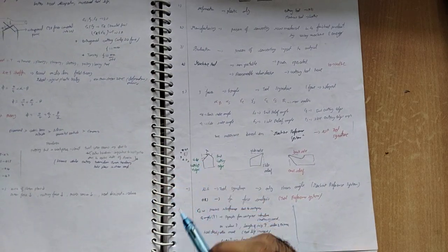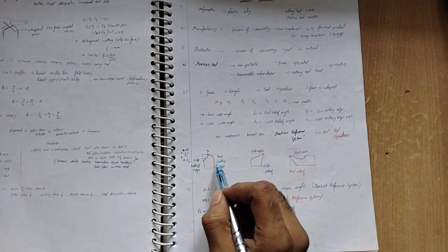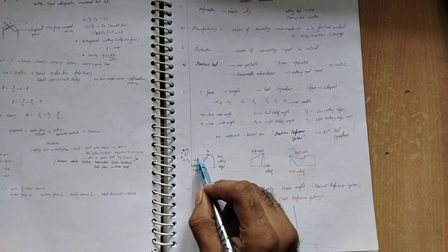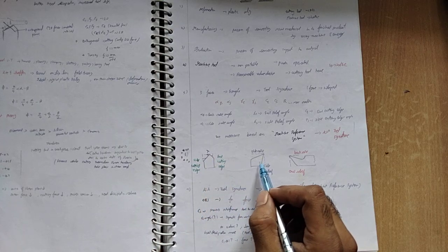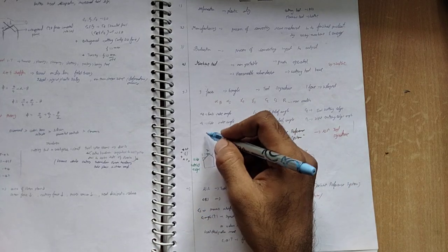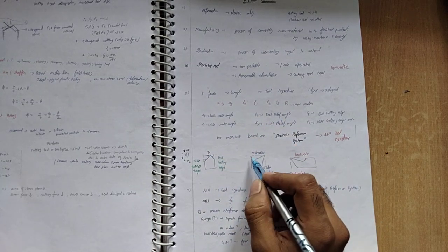When you see the image from the top, you can see this is the end cutting edge, a small one. This is the principal angle, and this one is the side cutting edge. This smaller thing is the nose radius. Whenever you see from the front, from this side, you can see this is the side rake angle and this is the side relief angle. Entire thing is side.